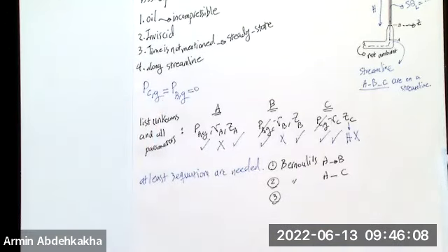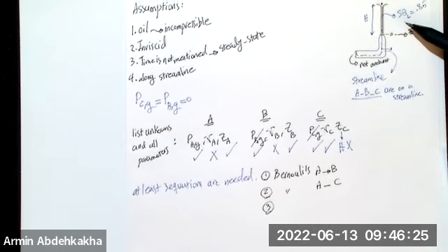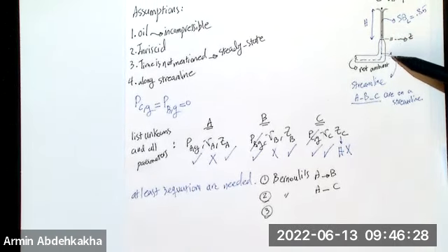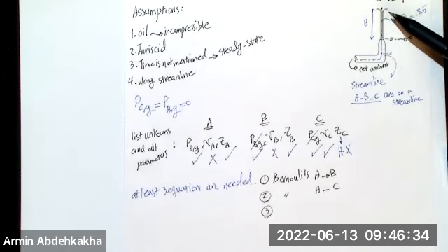Yes, we can, but this is not going to give you anything more than A to B. If you cancel out those terms, you will find out the 2 equations are the same. Between these 3 points on the streamline, you can write between A and B, then B and C. But applying it between A and C does not give you an independent equation, so it's not useful.